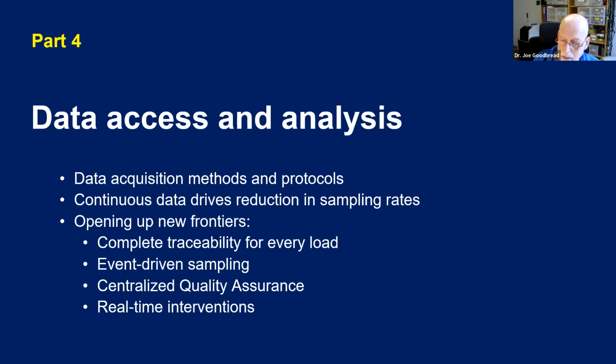So in a typical use case, you can monitor the general trend of the viscosity using the inline viscometer, and then periodically compare that with laboratory results. So you can use the trend data to see how well the viscosity is tracking with the laboratory standards.